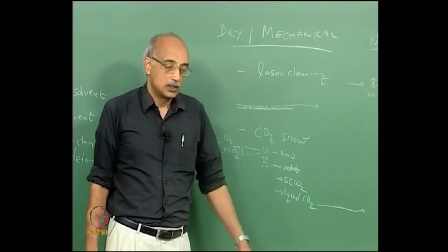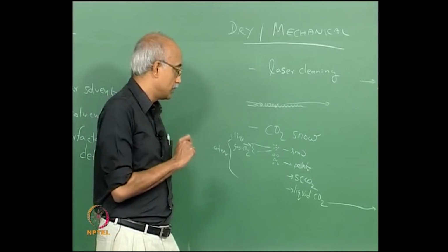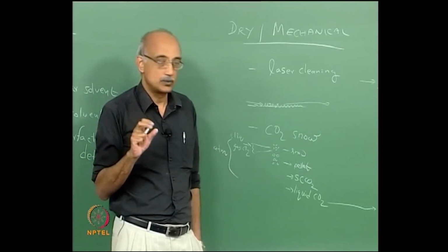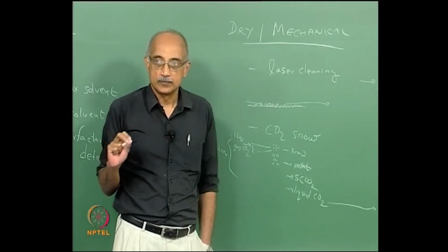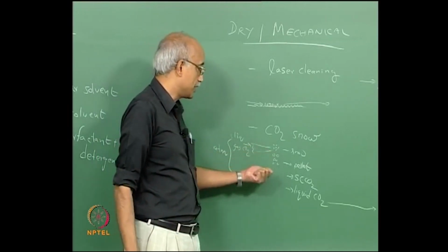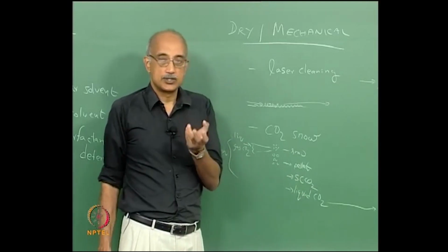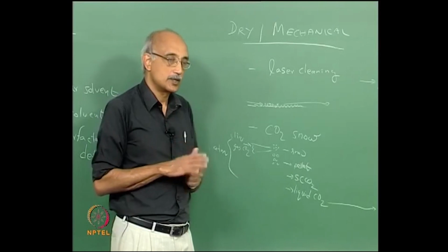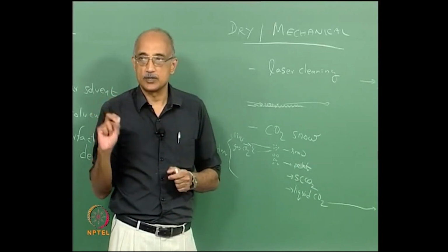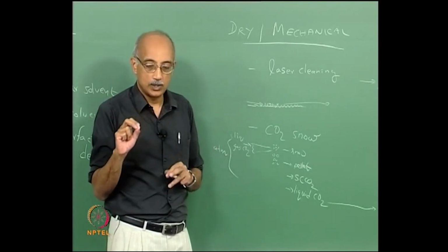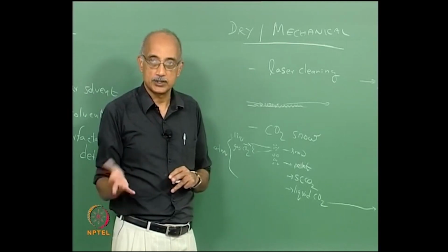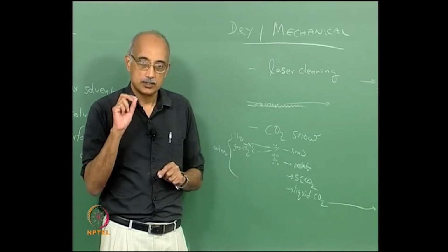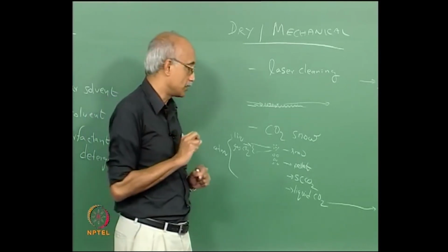Supercritical CO2 has the ability to remove materials selectively. So, you can actually tune it to remove the contaminant that you are looking for. Again, by controlling the conditions of expansion, you can produce supercritical CO2 with very different solvency properties and make it particularly effective for certain types of contaminants. So, if you know what the nature of the oil is on your surface, you can produce a supercritical carbon dioxide which is specifically optimized to remove that particular oil.